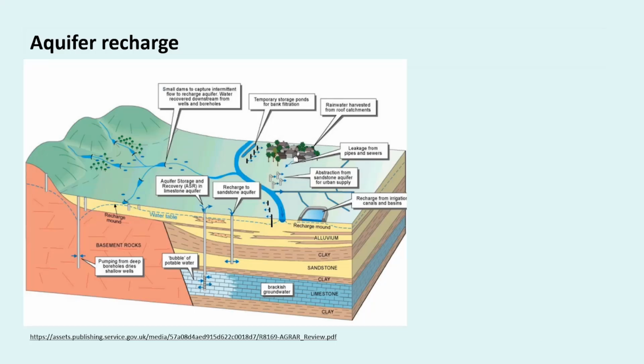So I mentioned that if a development is located over a groundwater aquifer, it might actually be possible to artificially recharge the aquifer using rainwater or high quality treated effluent from the development. The use of harvested rainwater or stormwater would require minimal treatment, but clearly the use of treated effluent would require very careful consideration to ensure that risks to the aquifer were minimized. And I think groundwater recharge is likely to be a niche option and would require considerable hydrogeological assessment to ensure that it is feasible, successful and safe.